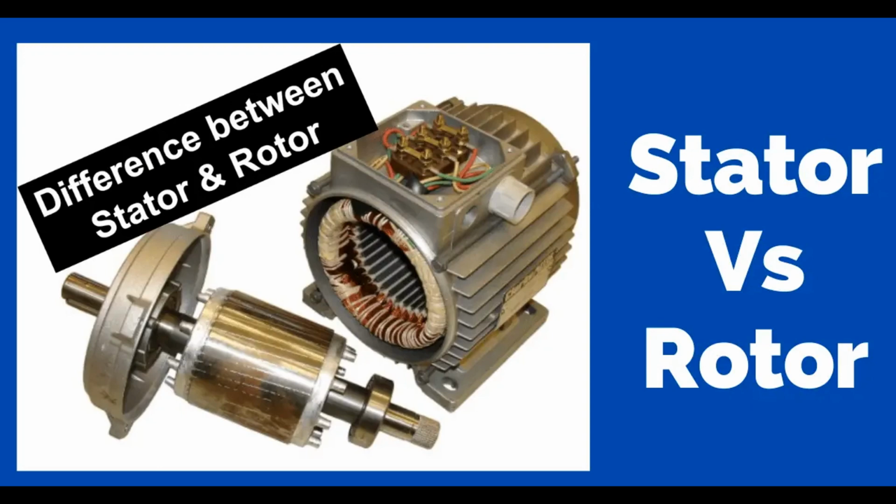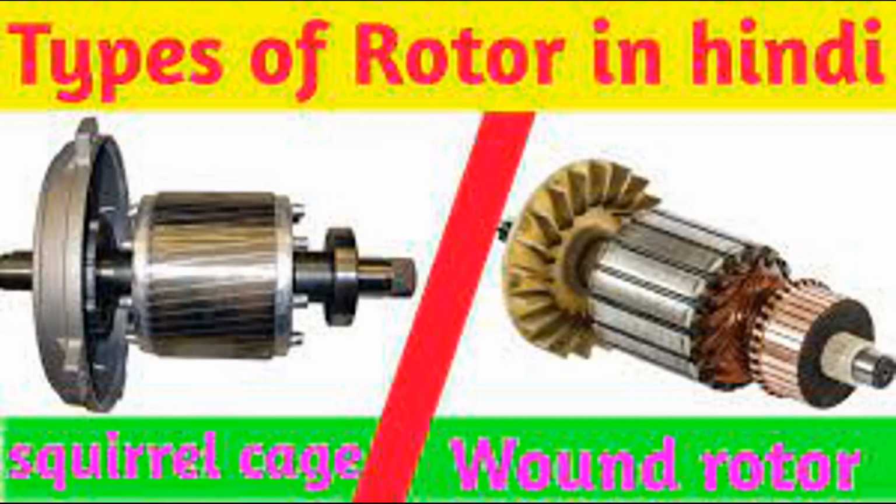Diode rectifiers. Rectification is accomplished using diodes. Diodes are semiconductor devices that allow current to flow in one direction while blocking it in the opposite direction. They act as one-way valves for electric current. Full-wave rectification. Most alternators use a full-wave rectification process, which involves using 4 diodes arranged in a specific configuration called a bridge rectifier. The bridge rectifier takes the AC input and converts it into a pulsating DC output.